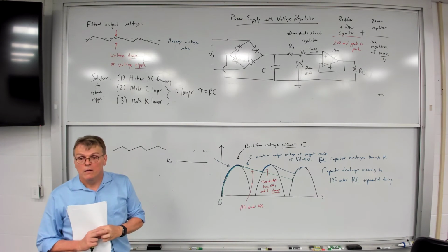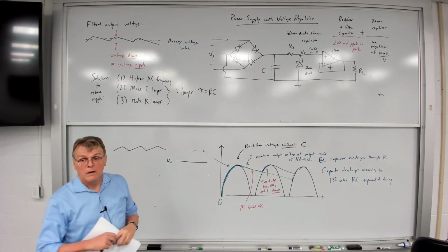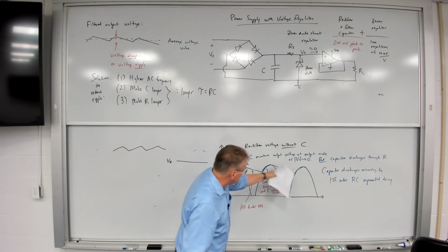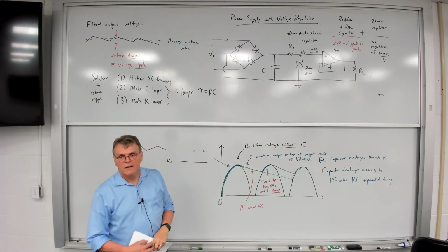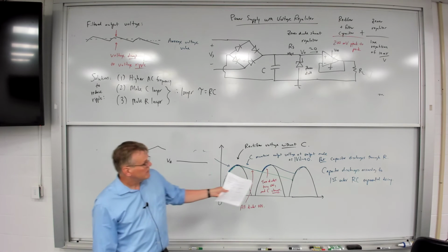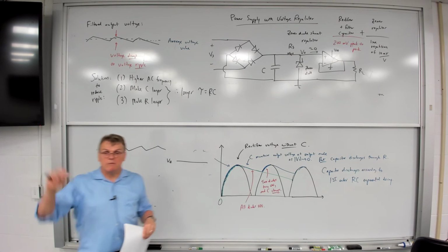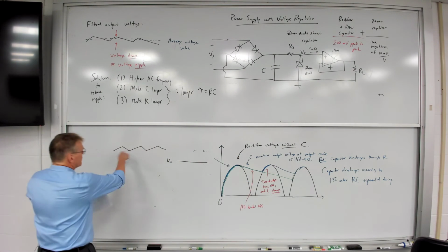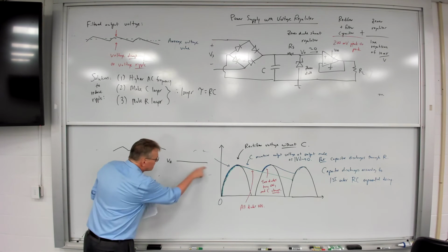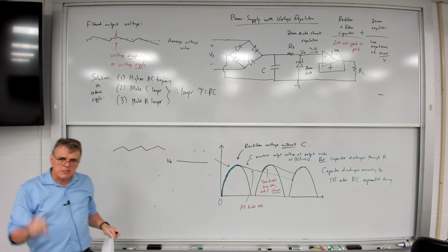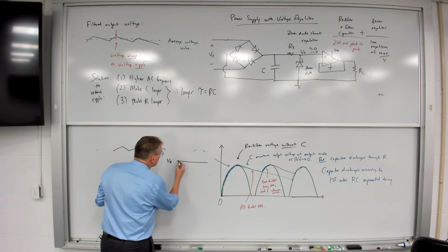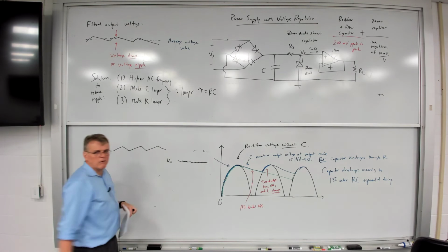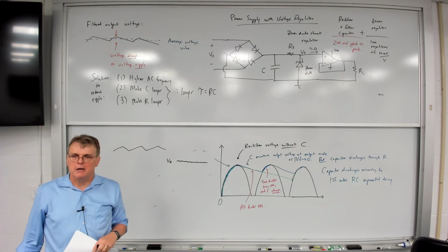So when you have the rectifier and the capacitor, the 200 millivolt peak, that's the blue line right there. Yeah, that was this blue line. And then the 2 millivolt peak would be your final output ripple at the output of the circuit itself, at the output of the Zener regulator. So what you're going to see is this. You'll have your input voltage with a large ripple. You'll have an output voltage which is going to be lower, set by the Zener diode. And then we're going to have a small amount of ripple on top of that, which is going to be the line regulation of the Zener diode. Okay?